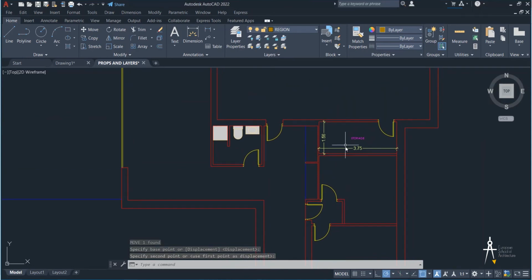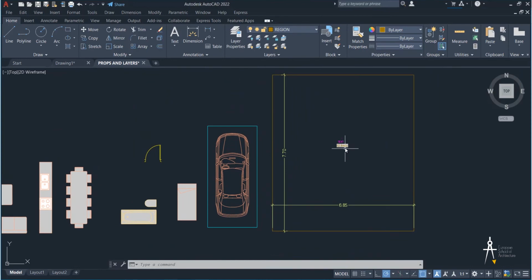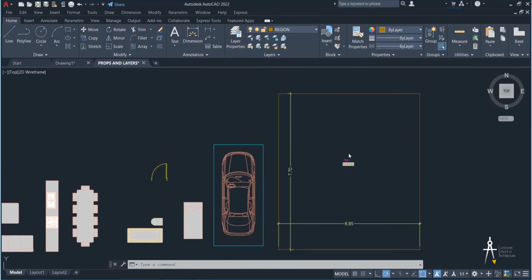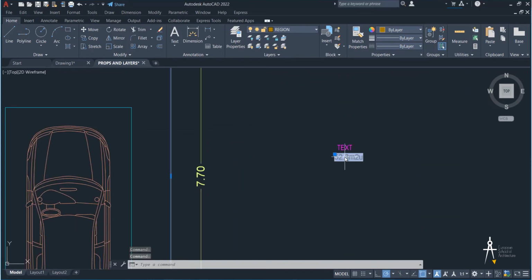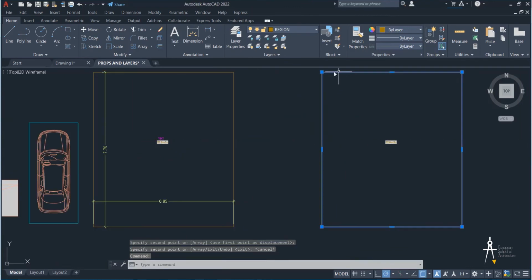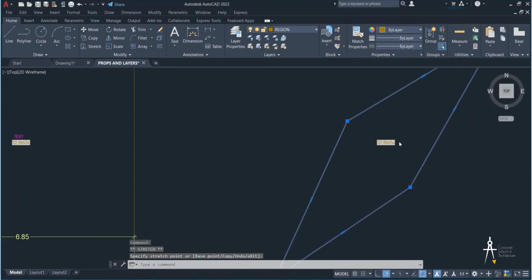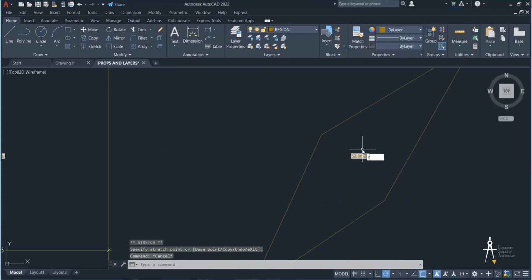And finally, something which is very interesting is the area. We are going to learn how to do this, but we've left an area, a polyline attached to an area. So if you copy these, put them aside, and you change the area, for example here, there we go, and you just type REGEN for regenerate, the area changes.